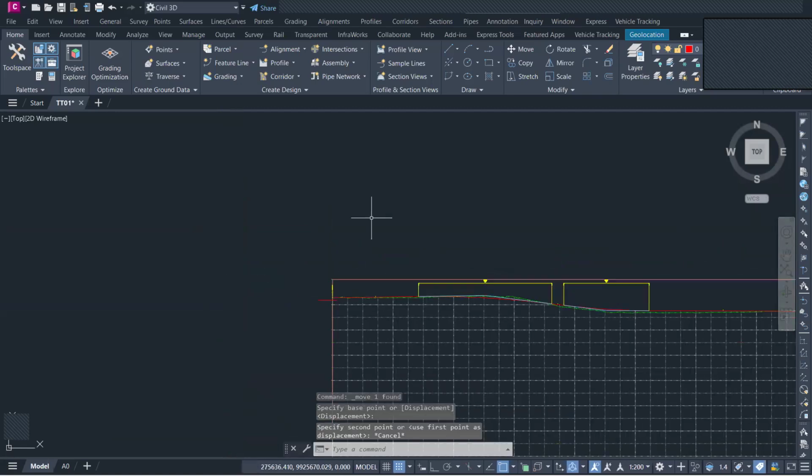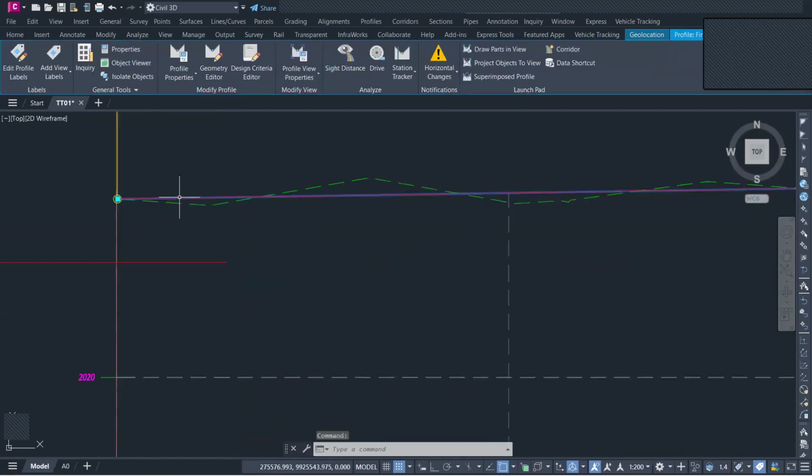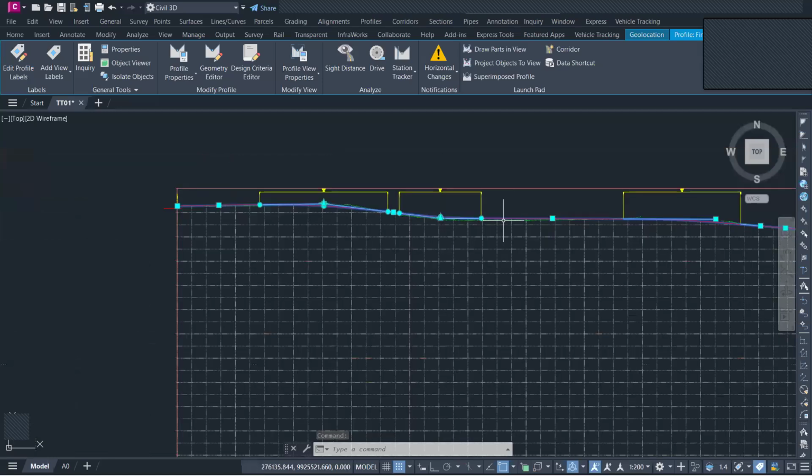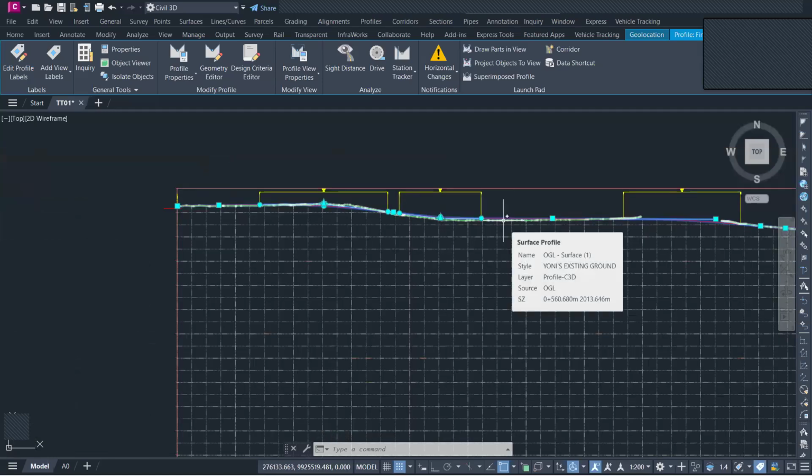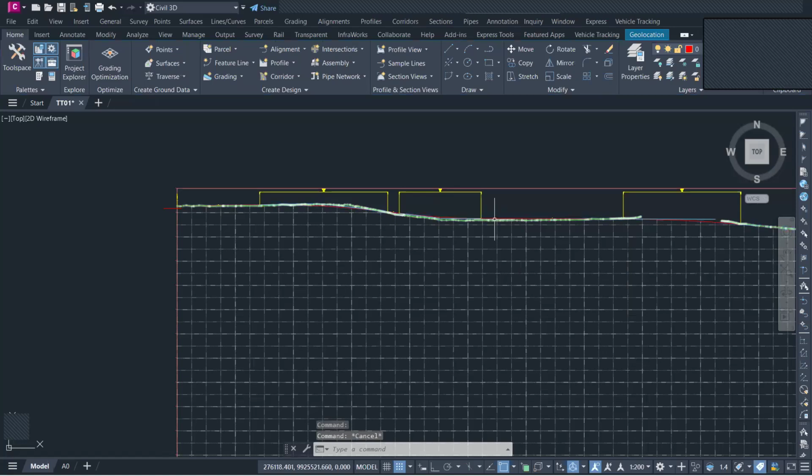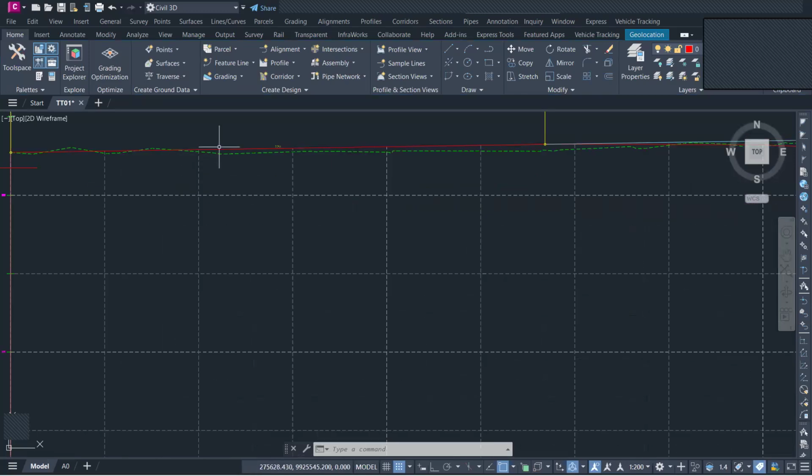But basically, what this would mean is that with this formation level that we've designed, that has met all the minimum requirements that we have in the road design manuals, we will have a lot of cut material so that we can be able to achieve the depth of the 300. So it means most of the works at this point will be excavations.